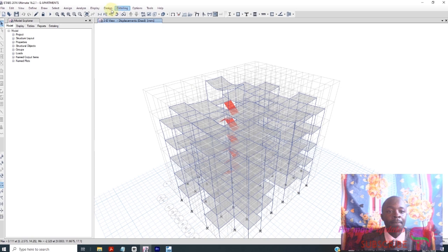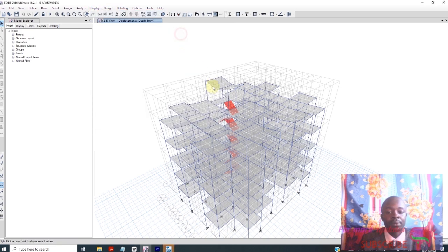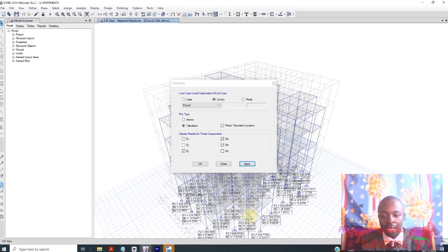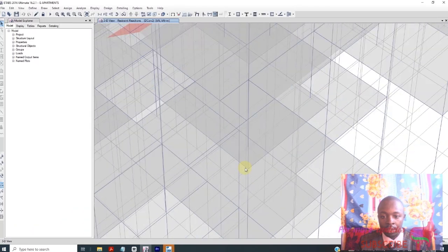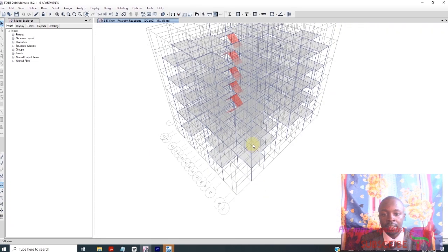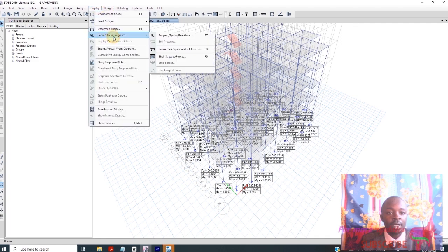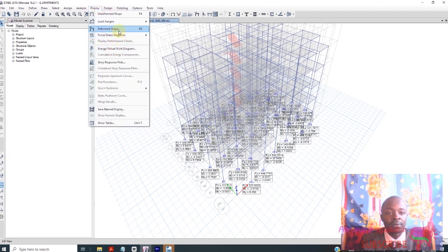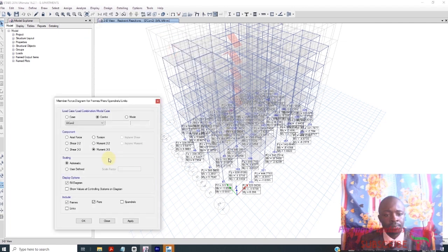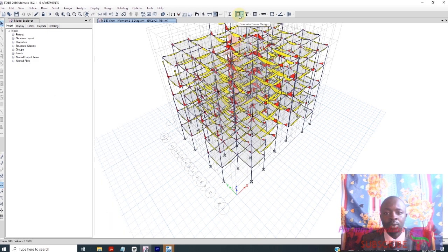You can check display. You can display force diagram, support reactions, combination 2, that is the most critical of Z, apply. And definitely the most critical has a load of FZ of 1049. So we can display other force diagram or deformed shape. For combination 2, you can display those. Then we can just go ahead and do concrete design.